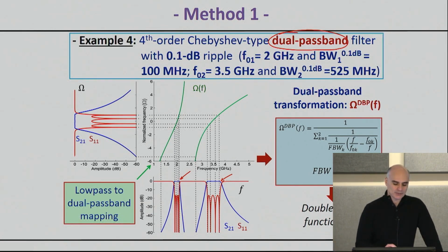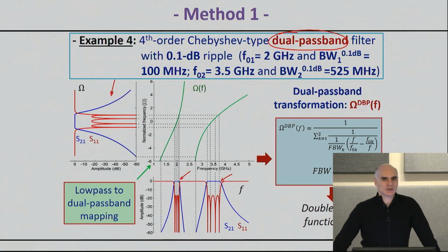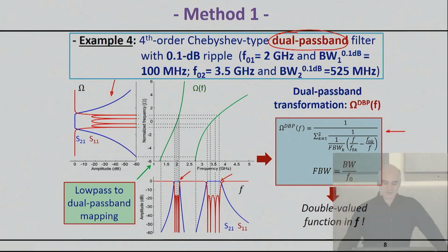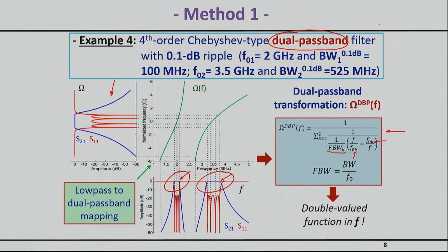I really want basically a bandpass filter with two passbands. And essentially, I still have to start from this low-pass equivalent prototype. So people have searched for equivalent frequency mappings, and here's basically the equivalent frequency mapping that you have to go from the normalized domain to the double bandpass domain. And by appropriately choosing, for example, the fractional bandwidth in each band, so here you have 2 bands, obviously, and 2 center frequencies, obviously, you can essentially successfully map the original response to pretty much any bandwidth you like for each band and any center frequency you like for each band. So it's a very powerful transformation that you can utilize.